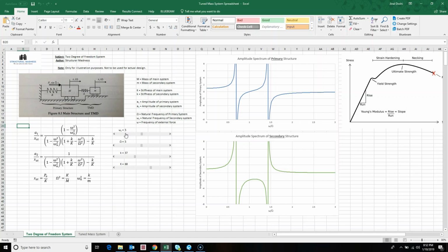So in case of wind, a structure oscillates back and forth only at its natural frequency. So the excitation is occurring at natural frequency. Now, if we calibrate the tune mass damper to the natural frequency of the structural system, just like in case of Taipei 101, what you can achieve is, even at very high external forces that are trying to excite the structure, the structure will not move at all, surprisingly. It will be the damper inside the structure that will be moving.